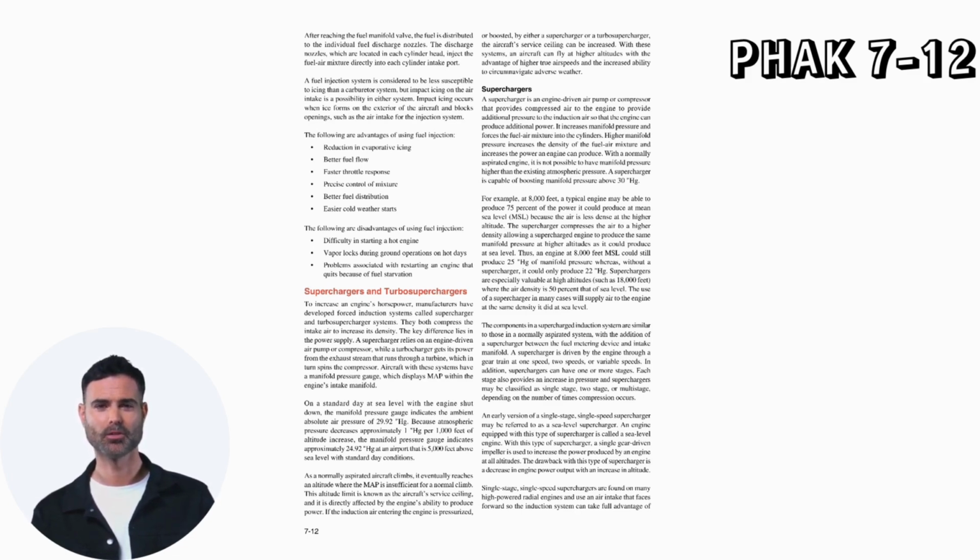Impact icing occurs when ice forms on the exterior of the aircraft and blocks openings, such as the air intake for the injection system. The following are advantages of using fuel injection: reduction in evaporative icing, better fuel flow, faster throttle response, precise control of mixture, better fuel distribution, easier cold weather starts. The following are disadvantages of using fuel injection: difficulty in starting a hot engine, vapor locks during ground operations on hot days, problems associated with restarting an engine that quits because of fuel starvation.